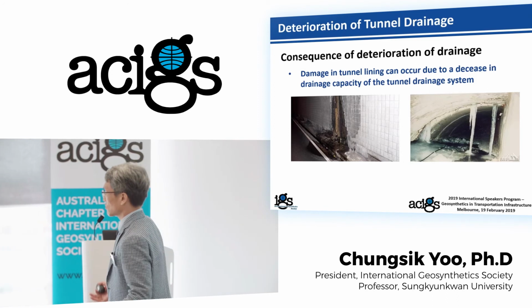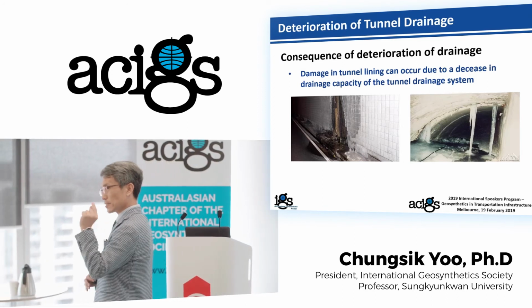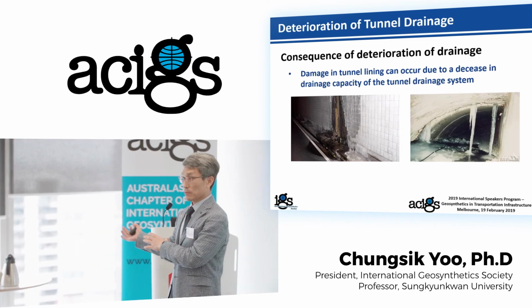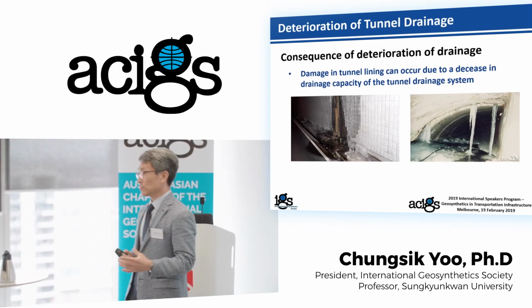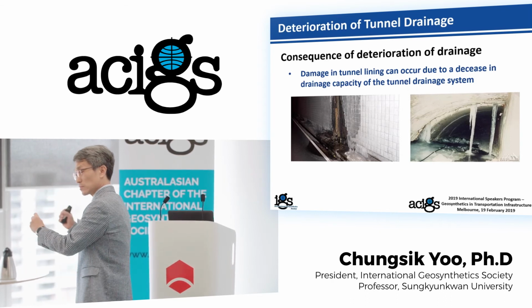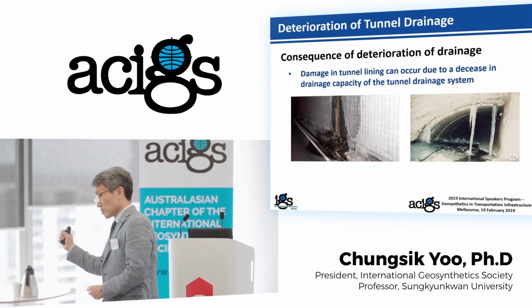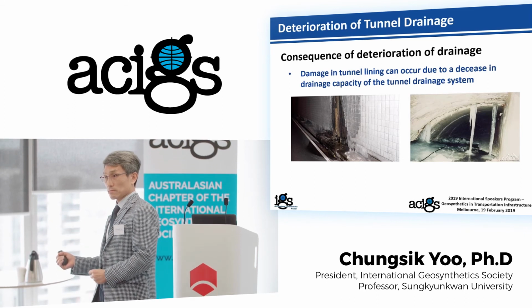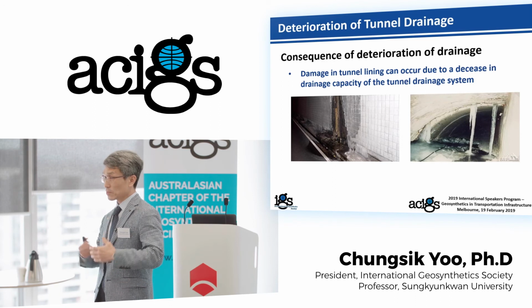So for the drained waterproofing system, at least we need some design guidance. We can adapt filtration design principles. We take the soil sample and check whether the geotextiles that you are trying to use are appropriate for that particular soil. That can be done easily.